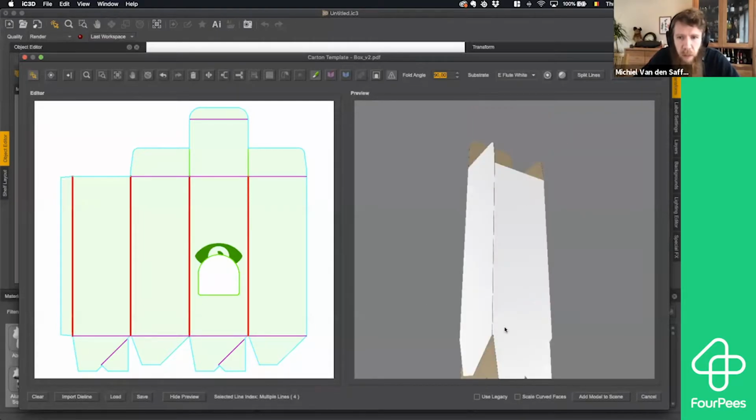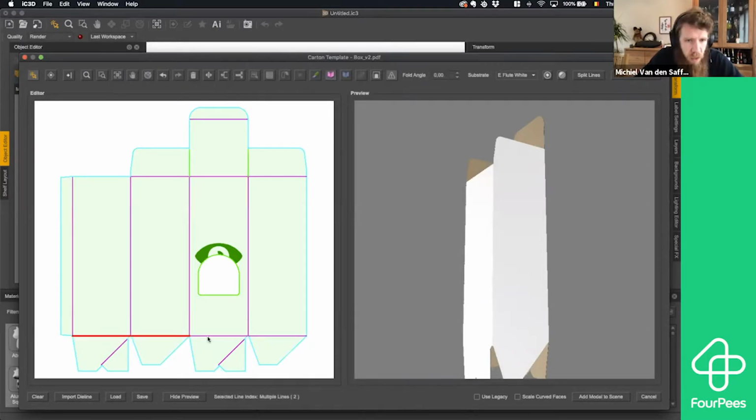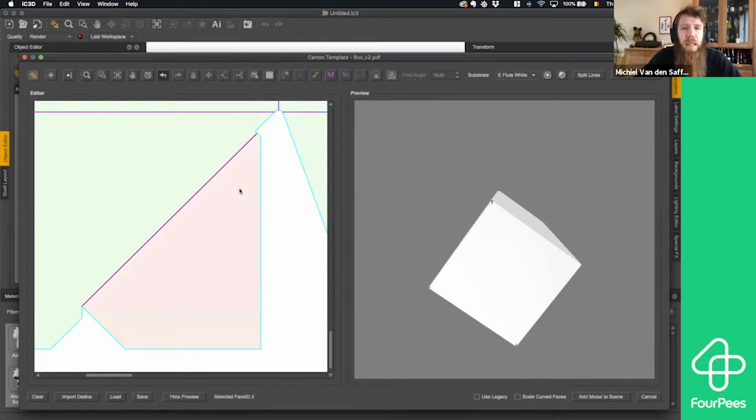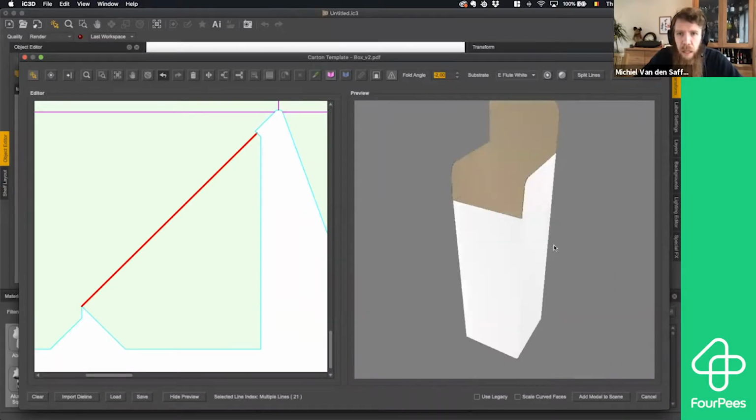At the bottom, well, this is always a little bit difficult because these things are never really 90 degrees. I think all of these ones are going to be slightly more than 90, so maybe 91 or 92 degrees. And then I have these lines. This is going to be a little bit of a pain to select. I think I still missed a piece at the top there. That should do it. Might be like -1 or -2, and that would create kind of the view where part of the design is, I was trying to zoom in, there we go, slightly hollow on the bottom, which is typically what you get with these kinds of locks. So I'll take all of those and I'll also put those at -2. There we go. So that bottom is now slightly pushed inward, and then all I have left is the top.